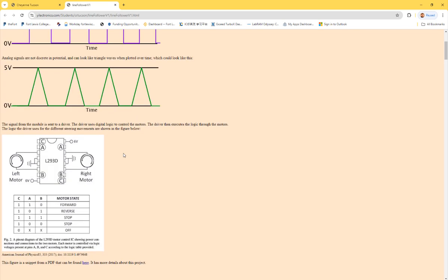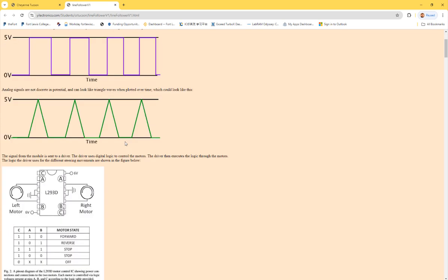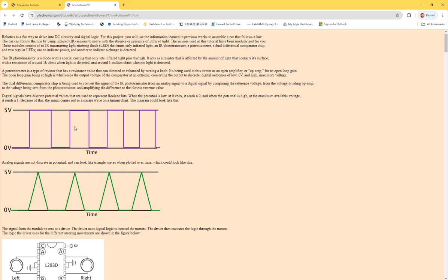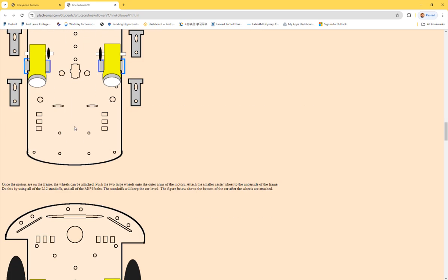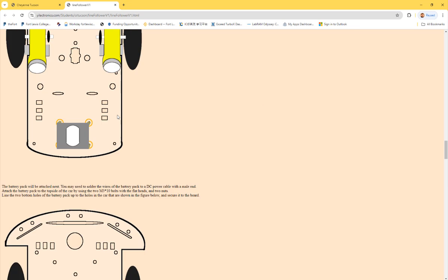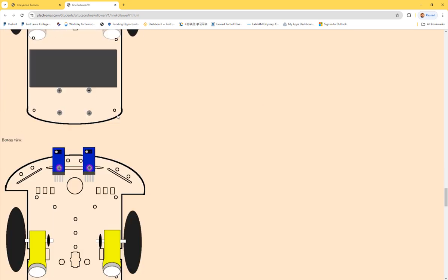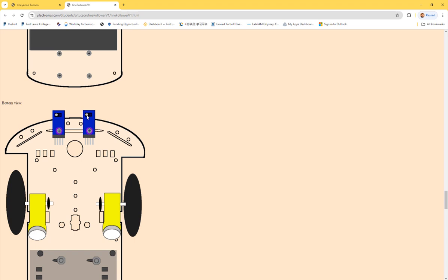All right. So it's a motor driver, and you can see this output is actually from the output of the op-amp as a comparator. I'm going to show you why the comparator is going to do this job very soon. And it has two DC motors, and these are the IR pairs receiving a reflection from the table. If it's a light color like a paper, it's going to reflect the IR light. And if you have a tape in the middle of the table or on the paper on the light color platform, it shows a black track.